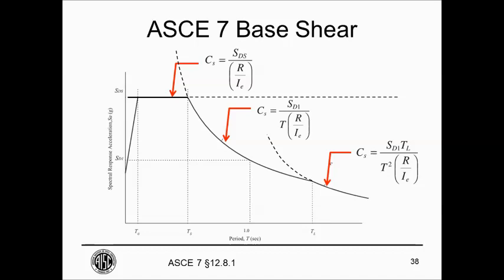Okay. Next question. Are below grade levels considered in seismic mass? That's a complicated question, and the technical answer is sometimes people consider them. So the code is purposely vague and says that the engineer essentially is responsible for determining where the base of the structure is.